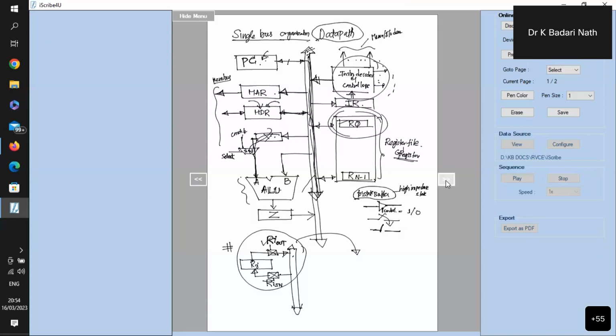We know that every register is nothing but a set of D flip-flops, because a D flip-flop is the one which can hold one bit of information. So now I will implement one bit of this logic. I will take one D flip-flop, with Q and Q bar. Now, let's say this is the bus, a one-line bus I have taken. Whenever I require, I should be able to connect the output of the register to the bus, so I will use one tri-state buffer directly and connect it to the bus.